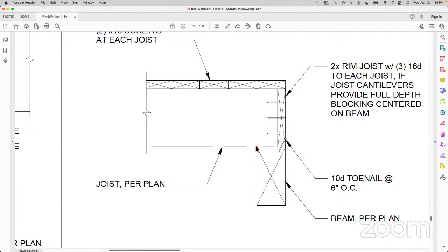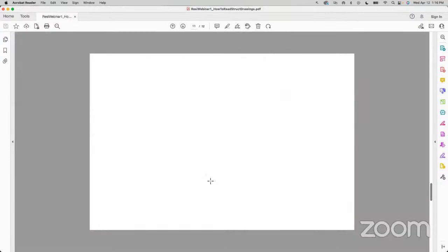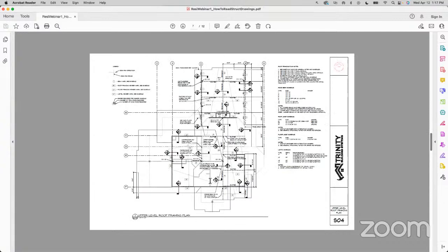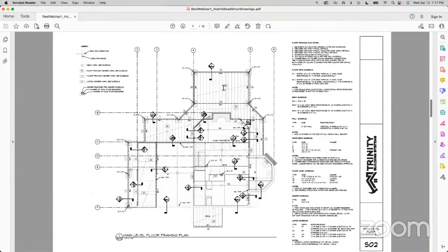And now we just need to determine the width of this beam here. So remember, we have 3 inches, and I know this feels like a lot of work just to get this bearing, and that's why I mentioned, I'm sure a lot of you just kind of already know bearing might not be governing, and you're going to put in a conservative value, but for the sake of completeness, again, we're gonna determine it. So beam per plan. So basically, we know we need to find the dimensions of the beam per plan and subtract that 3 inches. Let's zoom in. It's telling us this beam.